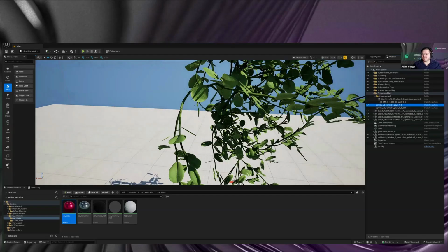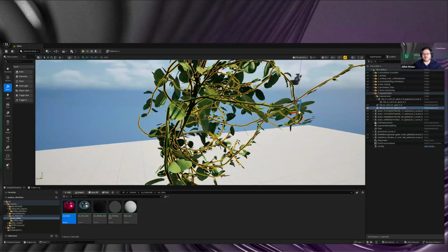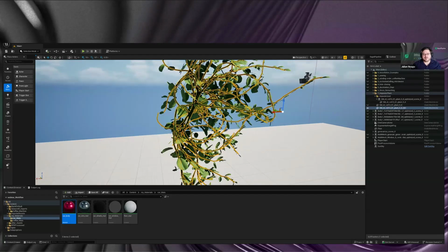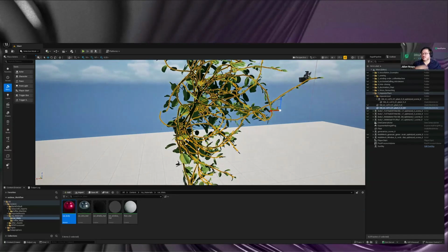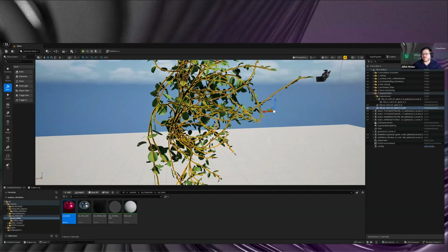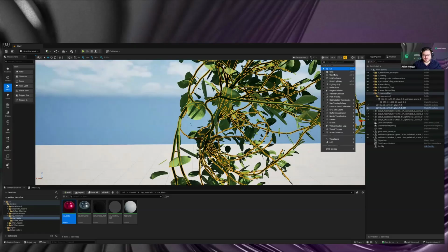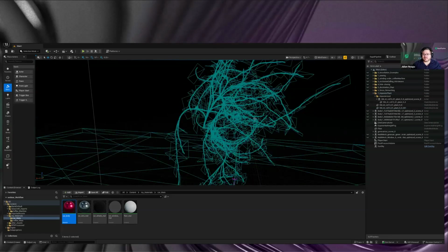And then for things like the stem here, for example, we would recommend rather using a decimation. It's also possible to do imposters here, then it would just line up different quads and project the alpha baking. That might look great from one perspective, but not from all of them. So for these parts, of course, we recommend going more with the decimation approach, standard simplification.